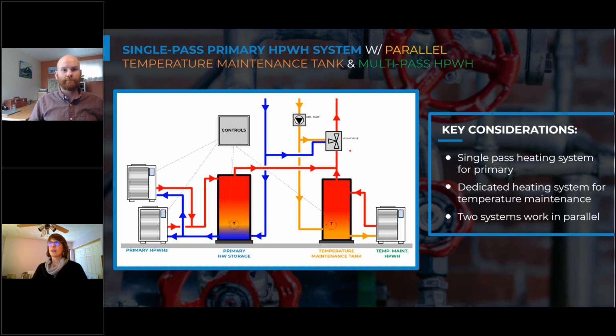Awesome. Colin, last question. What kinds of problems result from heat loss in the stratified primary storage tank? Yeah, so great question. So if we oversize this a ton, like if this is 3 times the capacity that we need, and we have a normal day of operation, we might not flow water through this entire tank or result in a changeover, essentially, like new water in this tank over the course of the day.